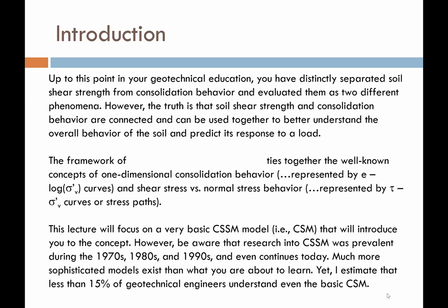And so if we connect these phenomena and develop a framework that can describe both simultaneously, then we can predict the engineering behavior of soils using that one single framework. So this framework that I want to introduce to you has become known as critical state soil mechanics.